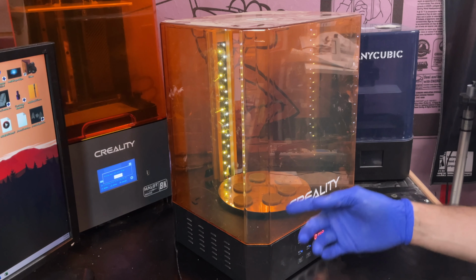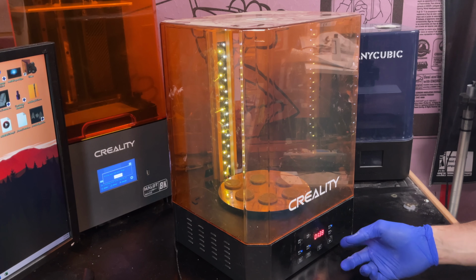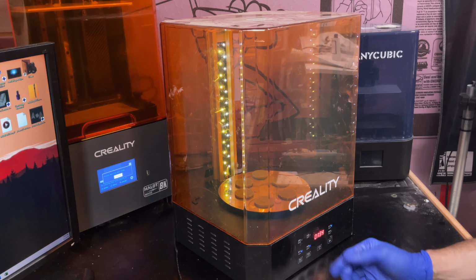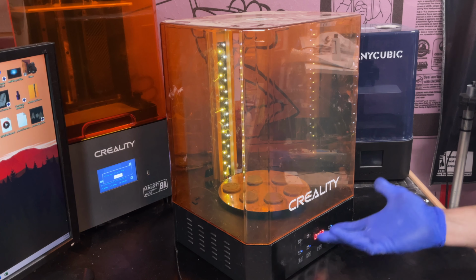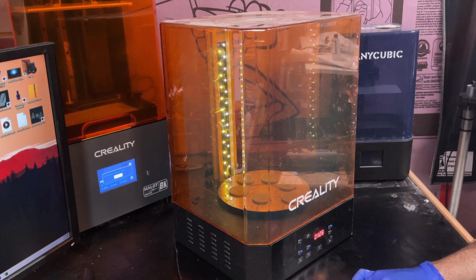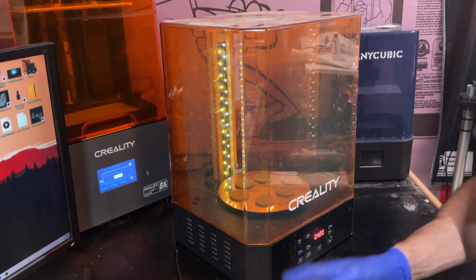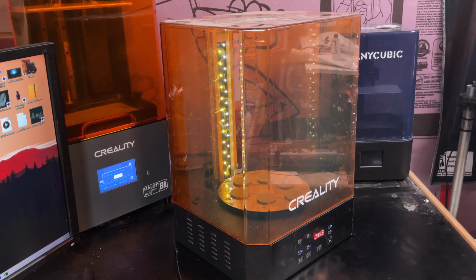I would like to mention, however, on flat objects like this, typically I will pause the curing process at about the 1 minute mark and flip them over to the other side. That way they have a chance to cure evenly on both sides. Again, since these are test pieces, I'm not too worried about it. I just did them to show you guys how simple it is to go all the way from something that you have on your computer to a physical item that you can hold and use.